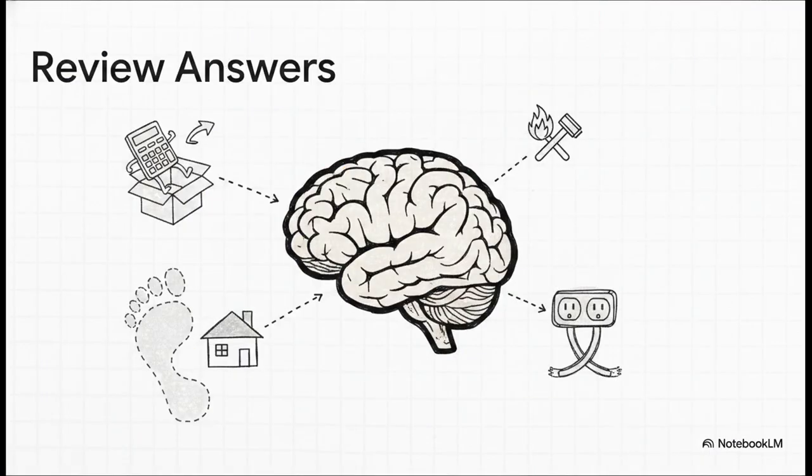All right, burn these details into your memory. You no longer go to Chapter 2 for the math. You navigate straight to Article 120 in Chapter 1. When you're doing the math, use 2 VA per square foot for your overall home service footprint. But, and this is the big but, to ensure the home is wired safely without overloading, you must keep your localized branch circuit density robust at 3 VA per square foot.